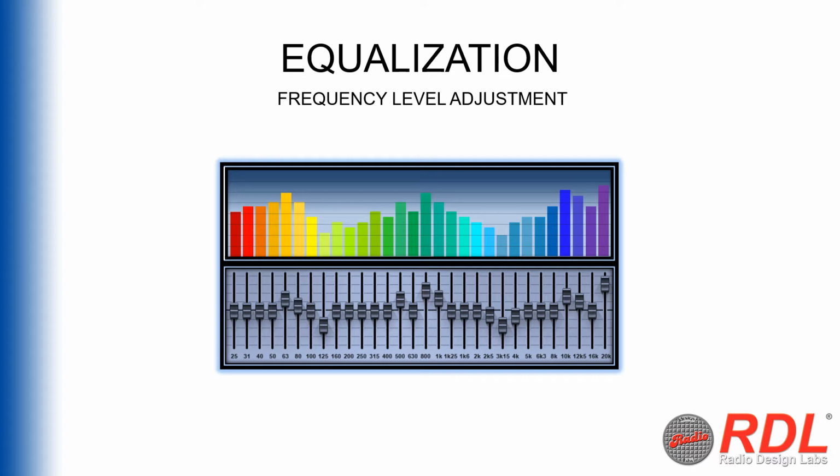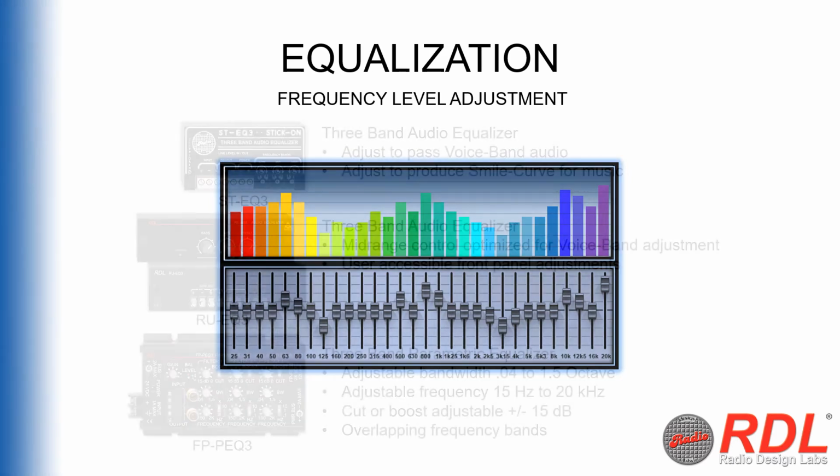More common equalizers are designed to adjust anywhere from 2 to 31 different frequencies. For example, tone control adjusts two wide ranges of frequencies called treble and bass. A 1/3 octave EQ provides 31 frequency adjustments commonly used to minimize rogue frequencies or to balance the overall frequency response in an environment. Other types of EQs, such as parametric, offer 3 or 4 adjustments where the frequencies and the size of their ranges are fully adjustable.